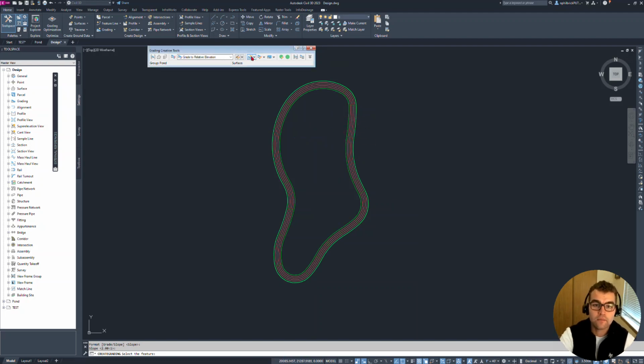All right, now the last step here is to create an infill. So we're going to fill in the center of our pond. And you'll know you created the infill when you see the diamond appear. So you notice that highlights here. We go ahead and click. There's our diamond. I'm going to hit escape. I'm going to close this out.